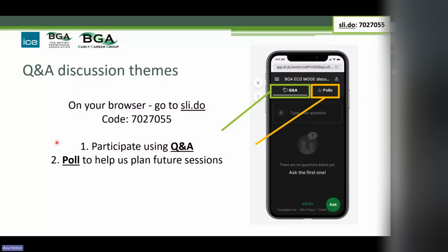Like you, I'm wary of multiple response zones in standpipe piezometers because you get leakage between them. You can do them in some locations with good contractors, but I've probably not specified multiple level standpipe piezometers for about 5 years because I think now that the vibrating wire piezometer is going to take over.